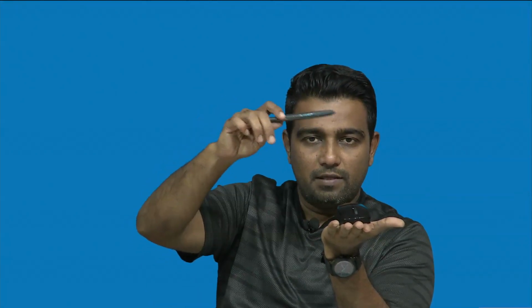So, just to quickly recall, we have a tissue placed on a glass slide, and we have a cantilever that we are pressing on the tissue, and depending on the elasticity of the tissue, the cantilever will bend. Now, this cantilever is embedded with what? Piezoresistor. So, when it bends, there is a change in the resistance of the cantilever. This change in the resistance can be equated to the elasticity of the tissue. That is what we have seen, right.